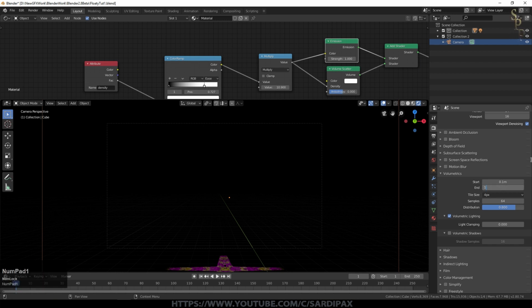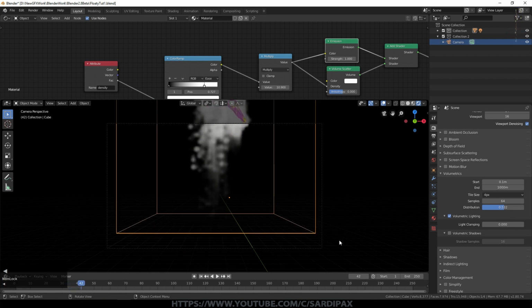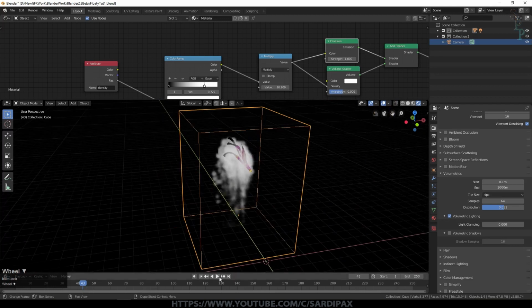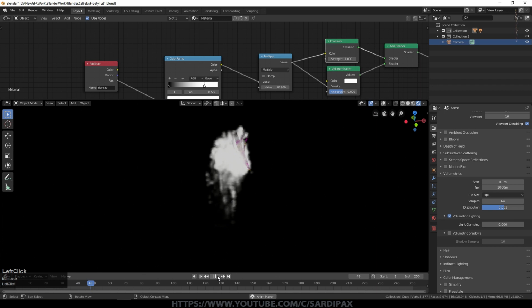And let's just put 1000 for the end distance on the volumetric effect. We'll turn this distribution effect down. So if we see how that's doing, you can see we've got a lot more smoke appearing. It is a little splotchy. Part of that is the resolution. Part of that is we can probably do more time samples, but it's giving you a general idea. If I turn the overlay off there, it's giving you a general idea of what we can get.